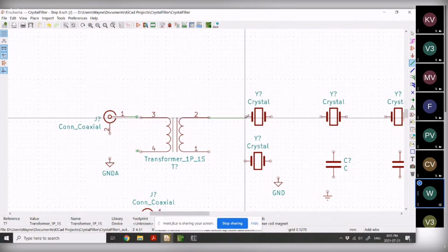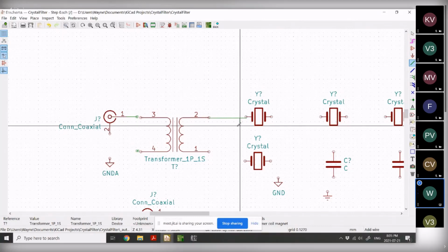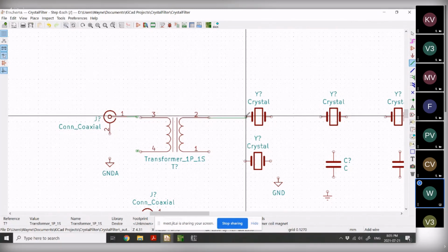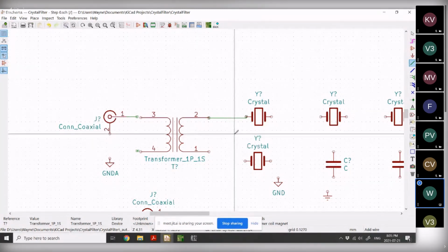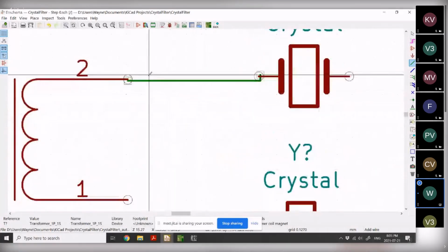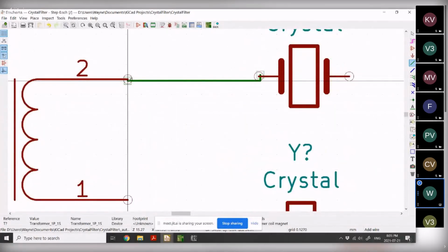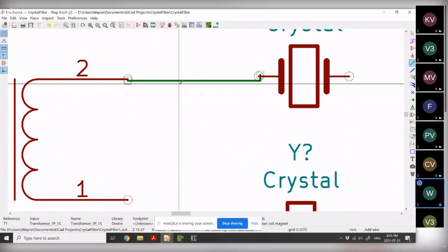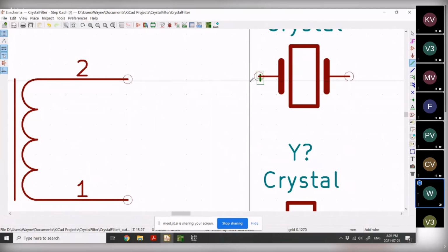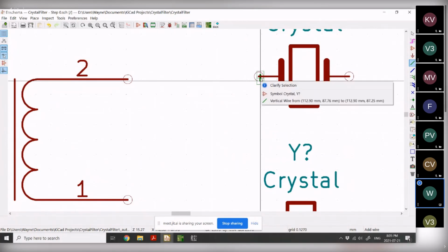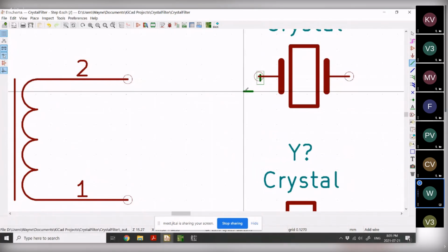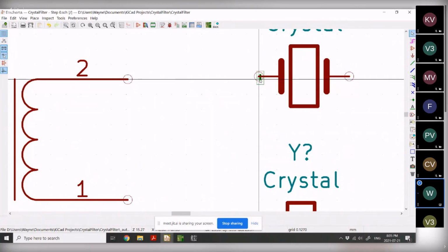Okay. The other thing you can see is these things aren't really lined up. I just want to close it here and double click it like so. Yeah, perfect. Okay. Do you see these square guys? They're very easy to get on your diagram, and what they're telling you is you didn't nail the wire. So, a lesson for this is put your diagram pretty big at the points where you're making the connections. So I'm going to pretend I'm dealing with a diagram that's much bigger than this. I'm using the delete key to delete these things I added.